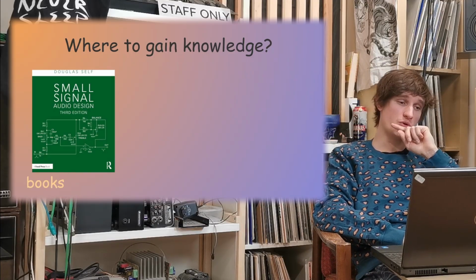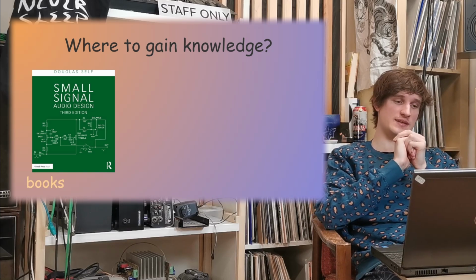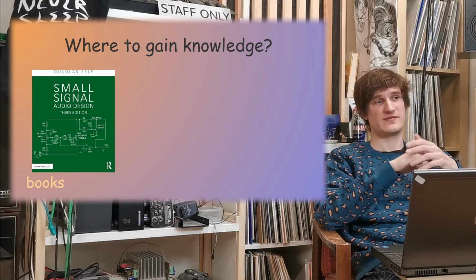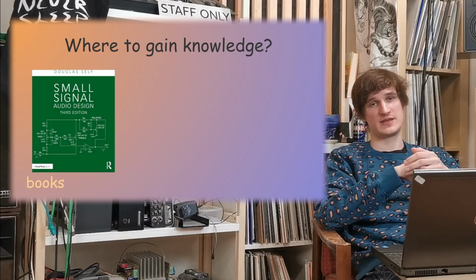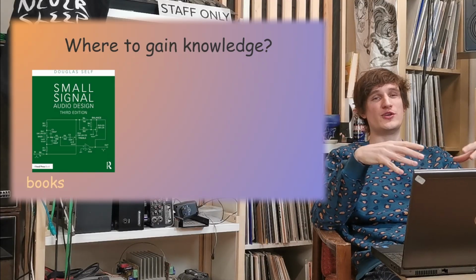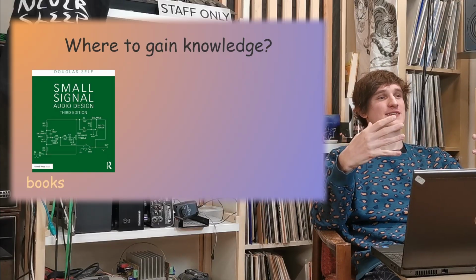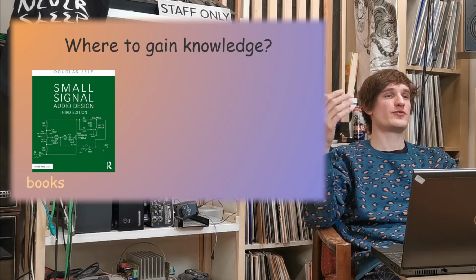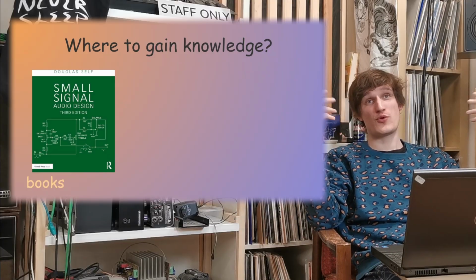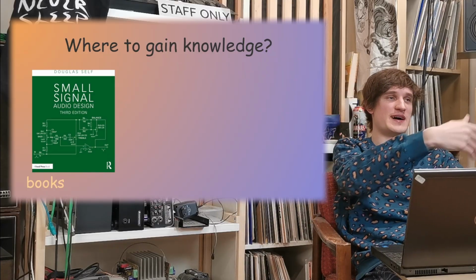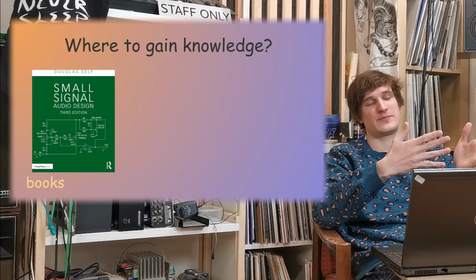So first of all, books. Again, I'm recommending Douglas Self's Small Signal Audio Design book. It's very mind-opening, especially for beginners, because when you read this book, you realize that when you, for example, want to have a 100 nanofarad capacitor, you don't just buy a random 100 nanofarad capacitor.